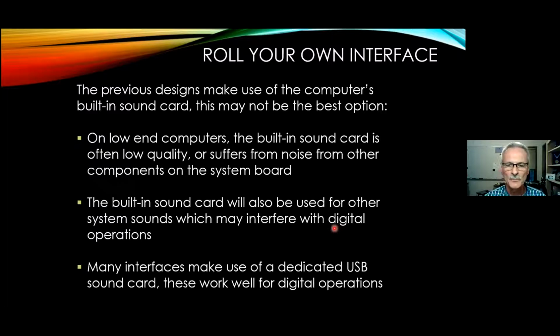That may not be the best option. There's a couple reasons for that. If you have a lower end computer, the built-in sound card may be of lower quality components. And the other issue I have seen with those sometimes is they pick up some of the noise from the other oscillators that are going on inside on the system board inside the computer. And so that could possibly affect your performance a little bit there.